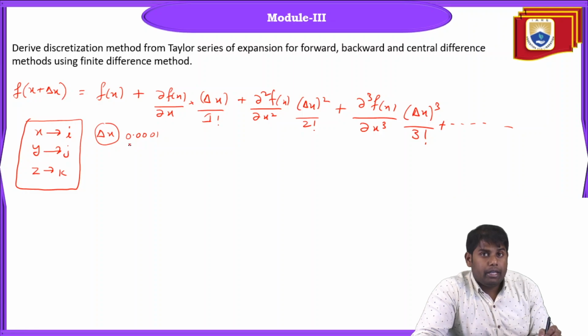It purely depends. There is no rule that you have to follow for delta x; in pure experimental and pure numerical simulations, based on the characteristics of the flow field you need to capture, we choose the value of delta x.